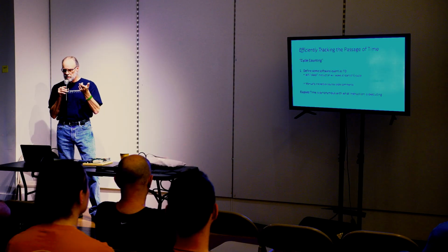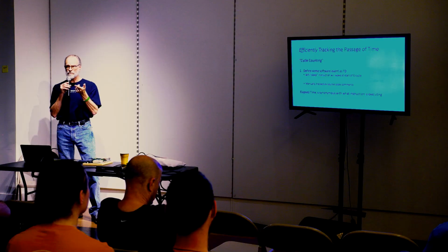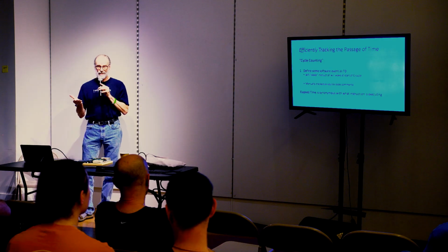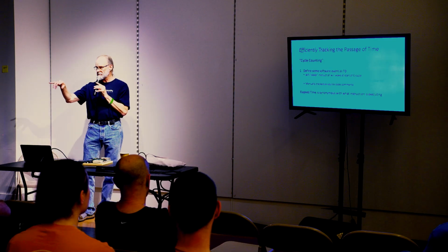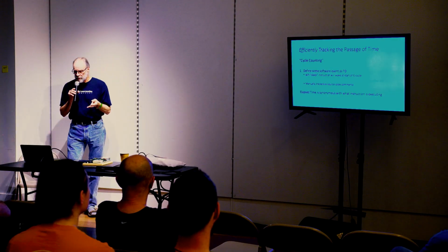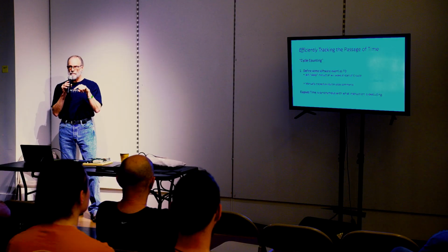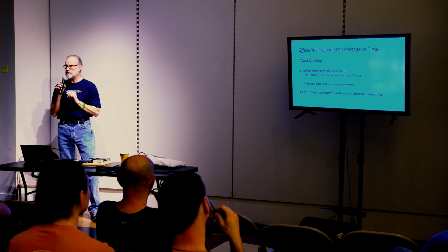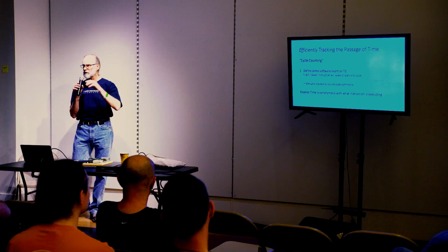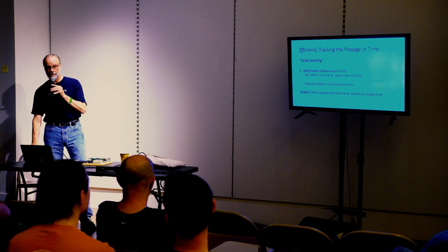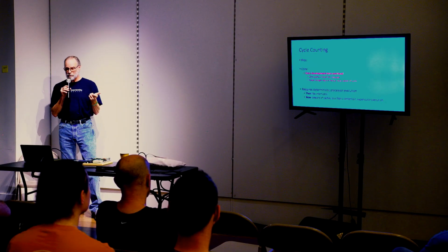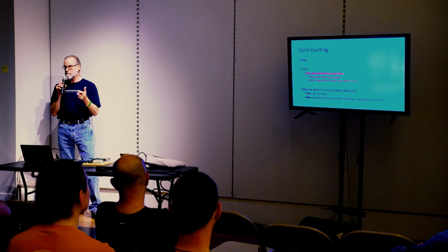Then what you do is you track the running sum of all the instructions that you execute in your code after T0. And you track it manually as source code comments. And so for each instruction, you just track how many cycles you're at. And what you end up with is a code base where the elapsed time is synonymous with whatever instruction you're executing. You know exactly when in time that instruction is going to execute related back to time zero. So you never need to read a timer. It's simple, it's precise. The coolest part is there is zero runtime overhead, none.